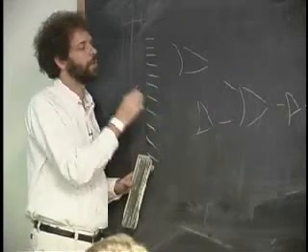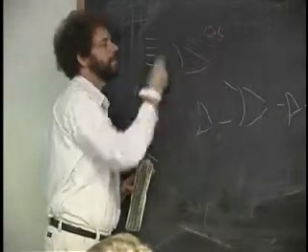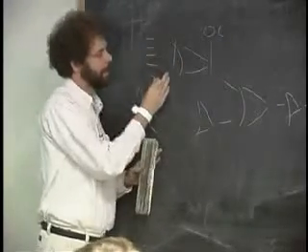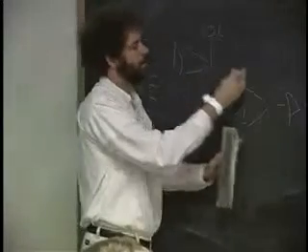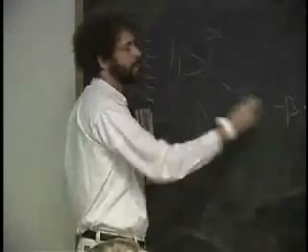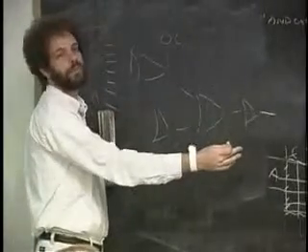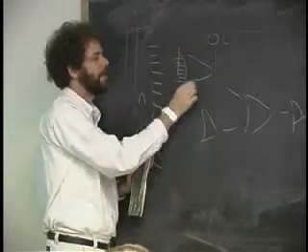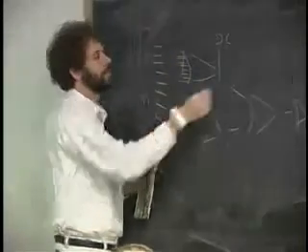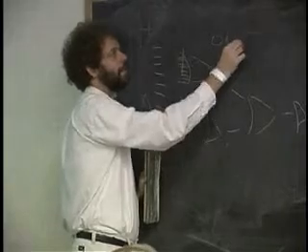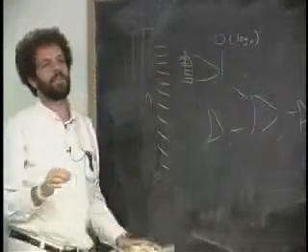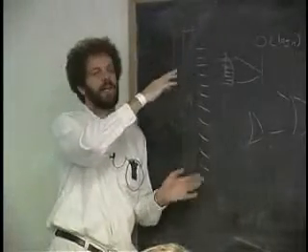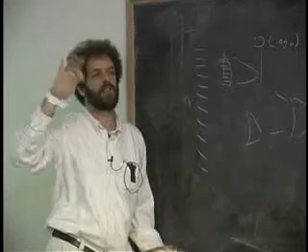And what does that mean? What's the order of growth of the speed of a circuit like this if each element has constant time? The bits come in here, they take constant time to go to here, constant time here, constant time here. So the height of the tree is equal to how long the circuit takes to work, which, if the number of inputs is n and the fan-in is bounded at some number, let's say 10, is order log n. So you cannot theoretically build an adder of a big number of bits n any faster than order log n, as n gets big.